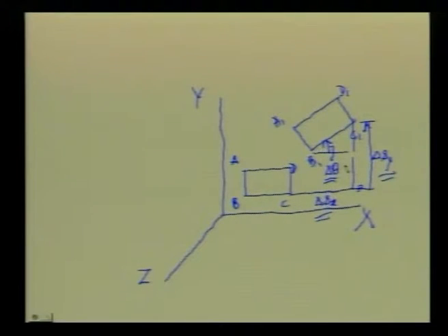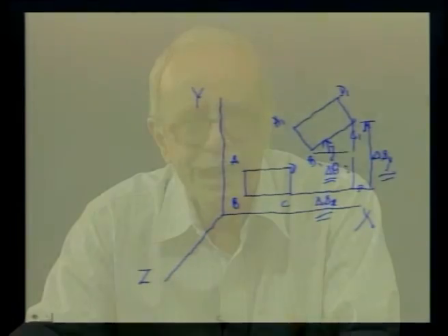Since three independent coordinates, namely delta Sx, delta Sy and delta theta, can completely describe this motion of the rigid body, it has 3 degrees of freedom. An unconnected rigid body in plane motion has 3 degrees of freedom. However, as soon as this rigid body is connected to another through a kinematic pair, one or more of these 3 degrees of freedom are restricted or lost.